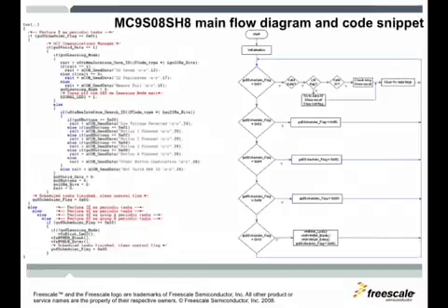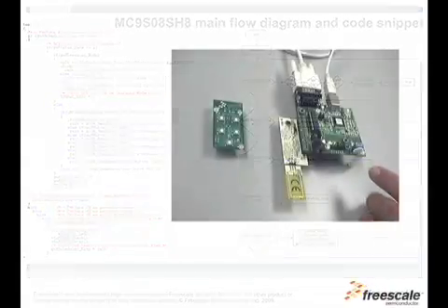This implementation is based on a scheduler that has 5 different time slices, each executing different functions at a different frequency. This project uses the smallest and the largest time slices. The smallest slice saves and identifies the different key fobs. It also displays messages through the serial interface. The largest slice handles the memory management and LED indication functions.